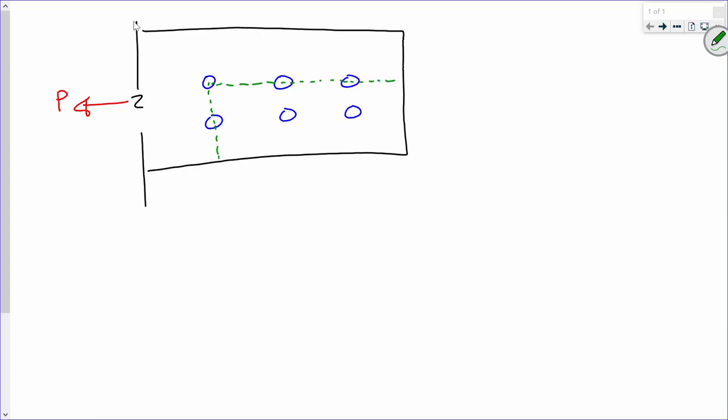I'm going to say that this is a viable failure path for 2 reasons. Number 1, it actually has a path in shear and a path in tension. You see that? Does it make sense that this long path down here is experiencing shear, like this one going this way? All right, so that's point 1. You actually have to have shear and tension to have block shear.